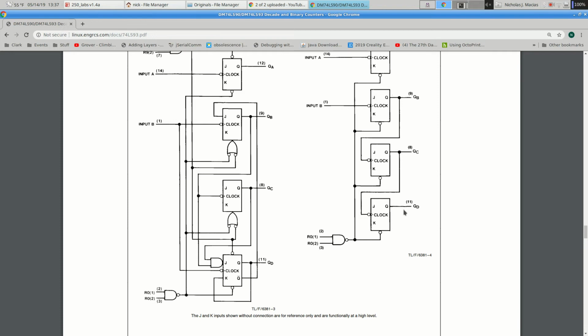Okay, you can squeeze this on one proto board if you're really good about it. A lot of times it ends up taking 2 boards. Not a problem either way. But you really want to think about this and test it as you develop it. Don't build a circuit with 6 chips and 100 wires and plug power in and it doesn't work. What do you do from there, right? It's a really easy circuit to test as you go.